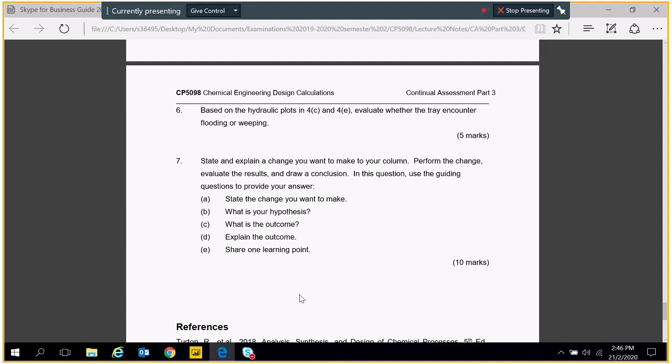If you want to increase the purity of benzene, let's say to 98 mole%, you change the 0.04, bring it down to 0.02. That's for toluene, 0.02. It means that the benzene purity now is 98 mole%. And then you run the simulation and see what's the effect. Is there any change in the column diameter? Is there any change in the reboiler heat duty? Any change in the condenser heat duty? Is there any change in the K factor? You can see the K factor. Any change in the temperature profile?